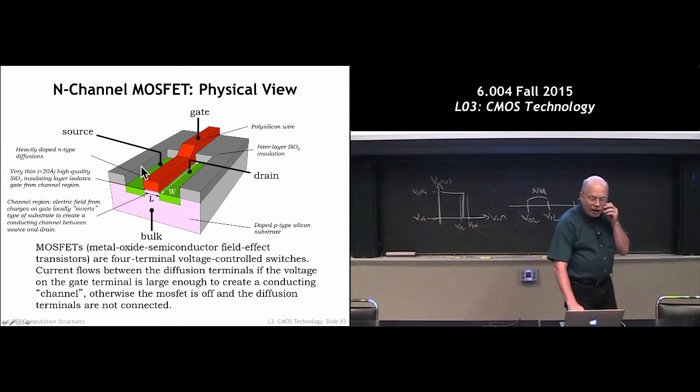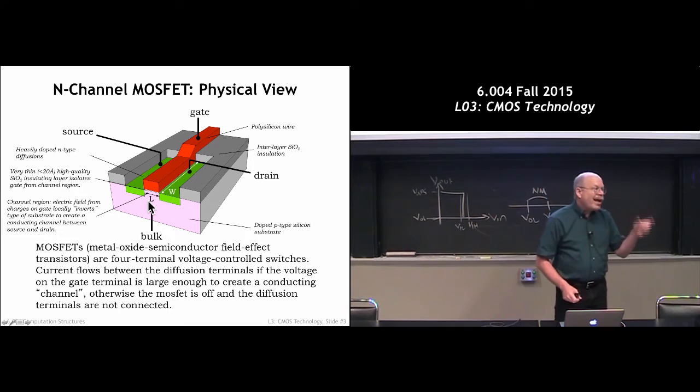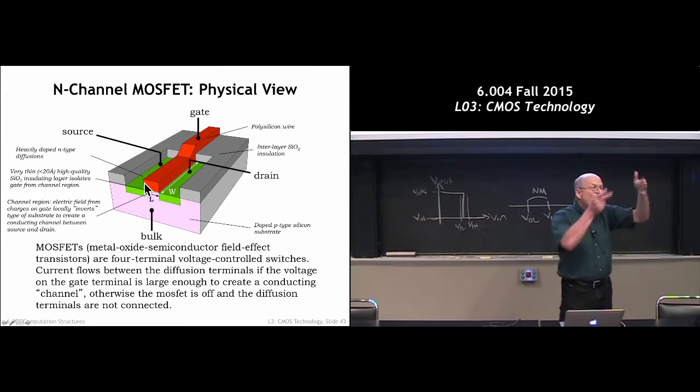Alrighty, so we tentatively want to make L as small as possible. If I tell you that you read in the Intel literature that they're building devices on a 14 nanometer process, the 14 nanometers or the 22 nanometers or whatever it is they're telling you, that's that dimension right there. That's the dimension they're telling you, the minimum width of the device.